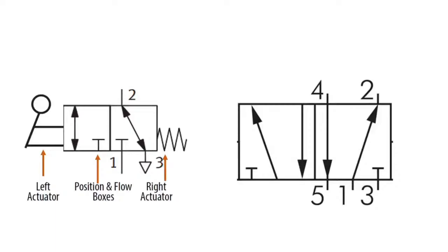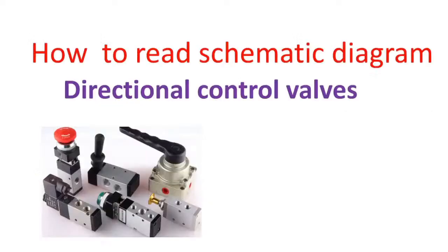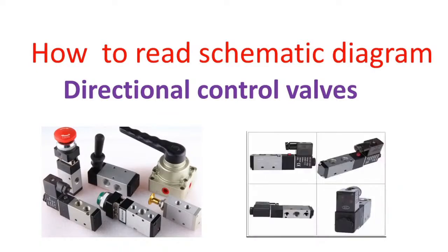Controls, sensors, solenoid valves, and input-output ports. Directional control valves perform only three functions: allow airflow, stop airflow, change direction of airflow. One of the basic directional control valves is the two-way valve, which is stop flow or allow flow. A garden faucet is a good example.